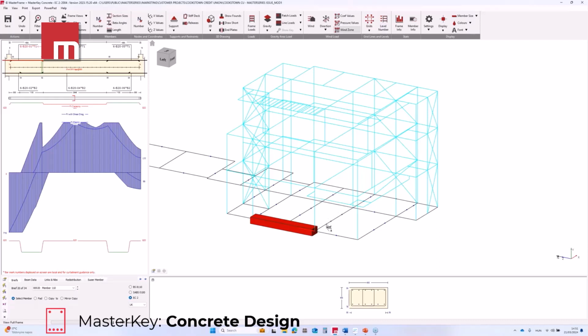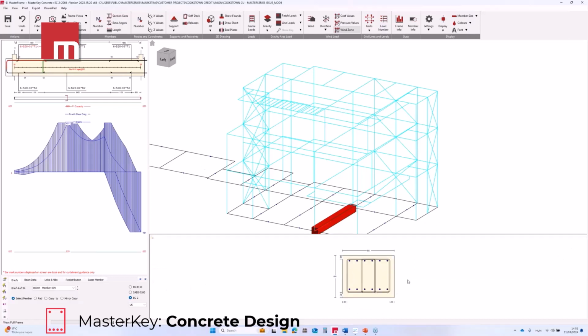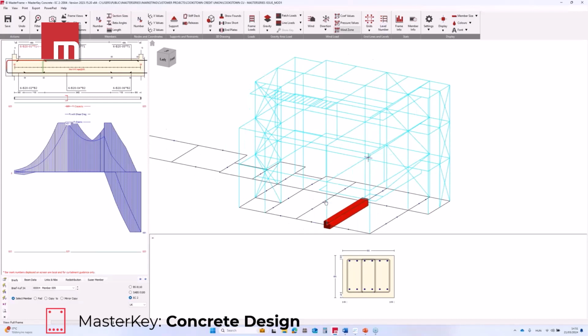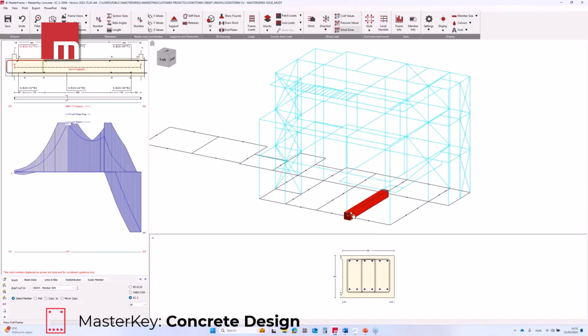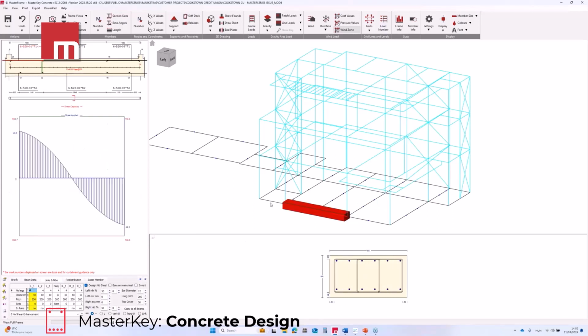The applied reinforcement is simple. 20 mil bars at both sides. So this is the used longitudinal reinforcement for all the ground beams. 20 mil bars both sides, and we have 4 legs of 10 mil links at 200 mil, and it works.